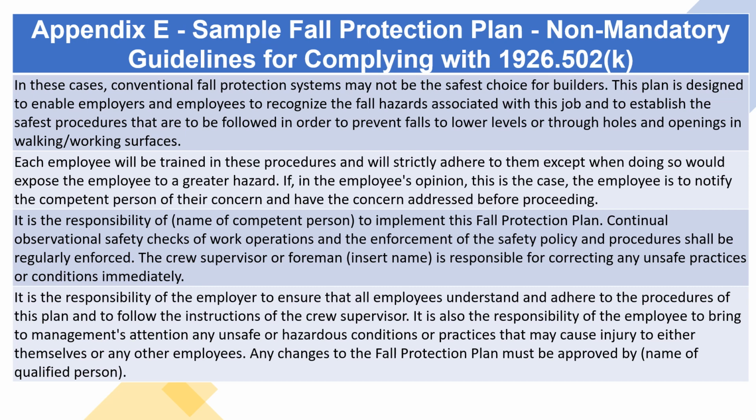This plan is designed to enable employers and employees to recognize the fall hazards associated with this job and to establish the safest procedures that are to be followed in order to prevent falls to lower levels or through holes and openings in walking/working surfaces. Each employee will be trained in these procedures and will strictly adhere to them except when doing so would expose the employee to a greater hazard. If, in the employee's opinion, this is the case, the employee is to notify the competent person of their concern and have the concern addressed before proceeding.